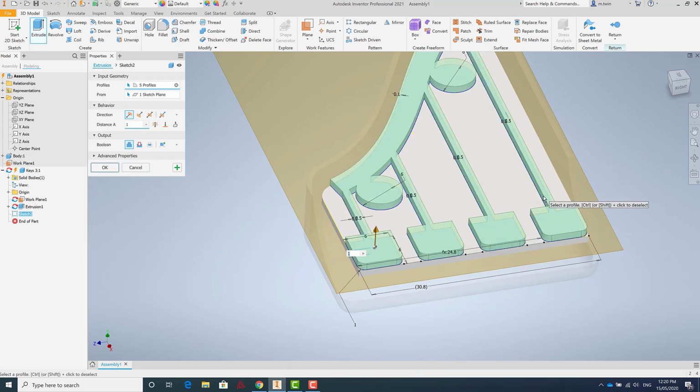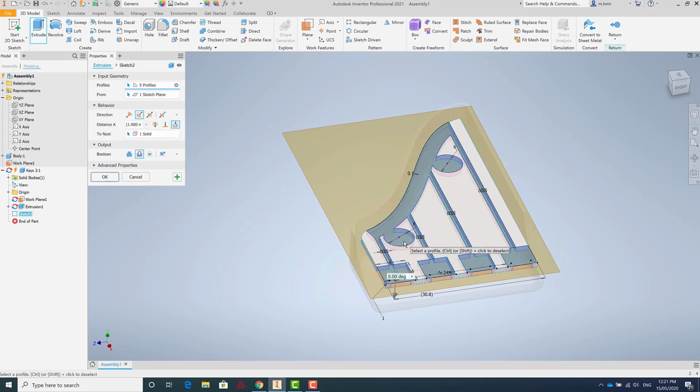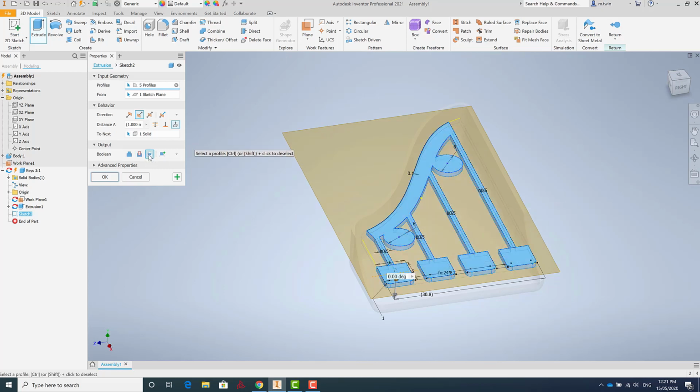and that shape. And what that gives us is it's saying it wants to initially extrude that up. So we'll extrude that down to next. Now we're into what's called these Boolean operations. Now these are mathematical operations to work out how something is extruded. You can join it, in which case really not much changes in terms of the shape. We can cut it out and you're left with the things that are sort of apart from that. Or what you can do is you can intersect it. And what that means is that only what's in the intersection between the shape you're extruding and the shape you're extruding into is left, in which case it's our little soundboard for our keys here, which is great. So we'll click OK.